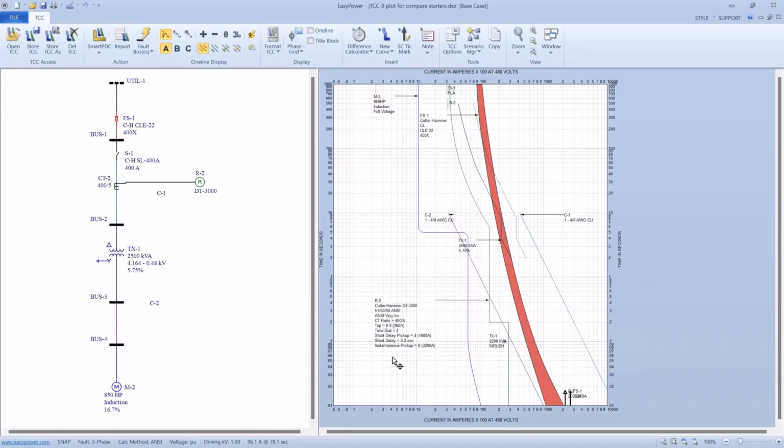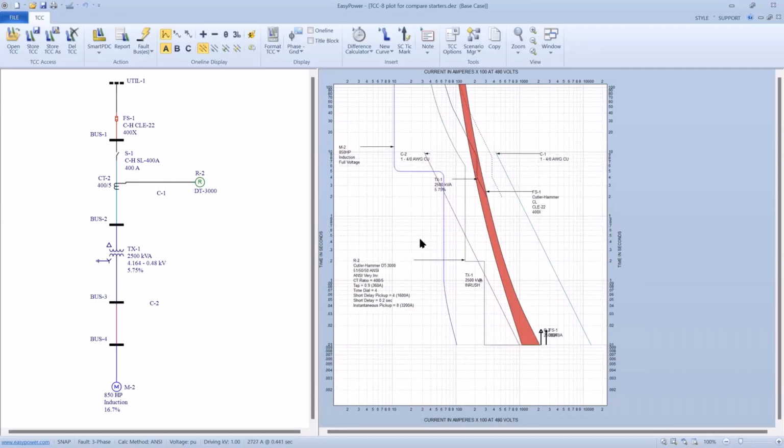I see my relays doing its thing. The motor circuit, the motor is pre-set up on the motor. Here's the fuse, the 400 amp fuse, and I don't show any effect. Well, there's no trip mechanism in the switch itself except for the relay. So the relay's tripping the switch.